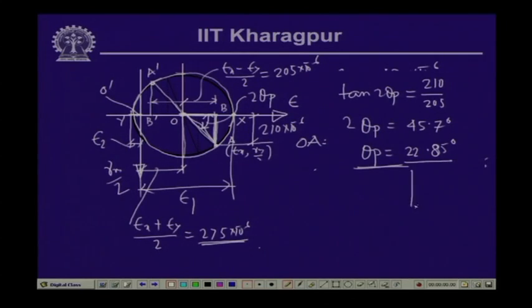Now, we have reference axes x and y. We will have to find out the state of strain at an orientation of the axis which is 75 degrees anticlockwise with reference to x, so we will find the strain along x1 and y1. When we take 75 degrees in the reference plane, in the Mohr plane that becomes 2 theta, which is 150 degrees. Now, from this particular reference point, if we go 150 degrees,